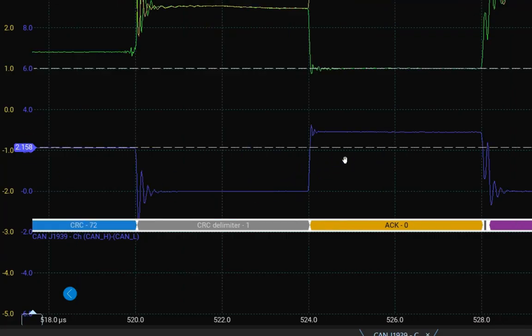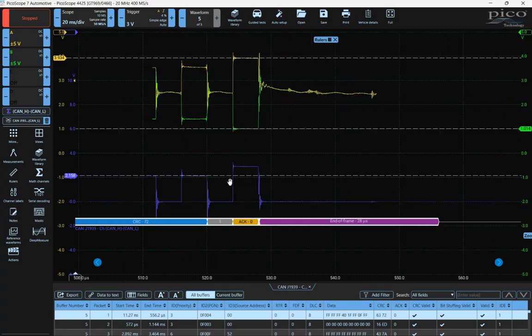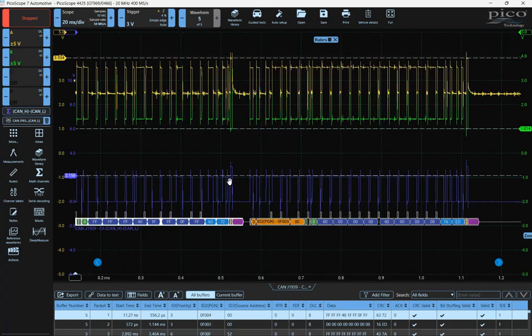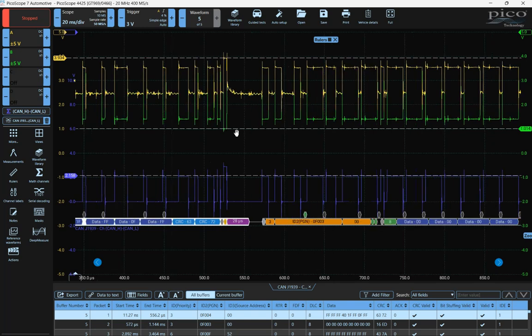We can also see that there is quite a bit of noise here. And as I said, most of this is because of the power supply in my bench and the common ground that I have for my laptop and my setup. So that does induce a lot of noise that you're not going to see on a real CAN network. But this does show you how robust CAN is. I'm still able to decode all of this. We have all of the other devices. Nobody is complaining or throwing error frames on the CAN bus, indicating that there's some message that they don't agree with, that they've misinterpreted a logic 1 and a logic 0 someplace, a dominant and recessive bit. But anyways, this gives you an idea of how robust CAN is.